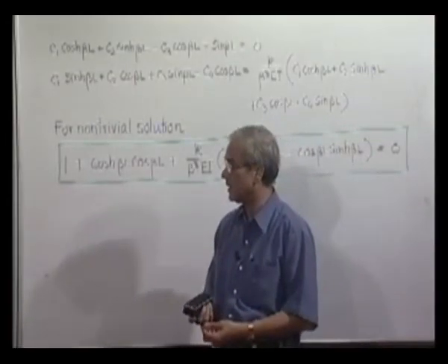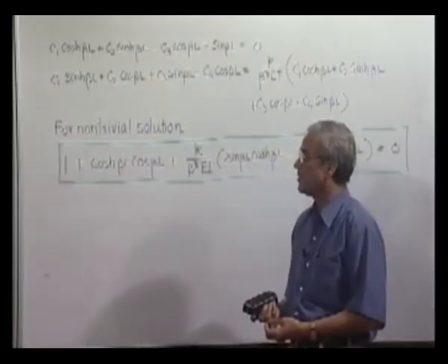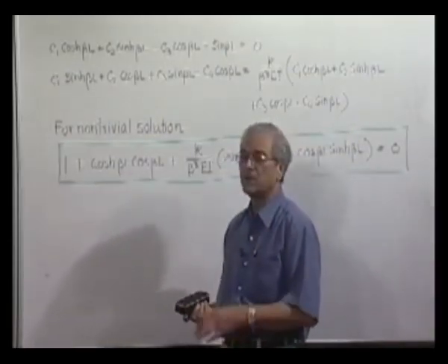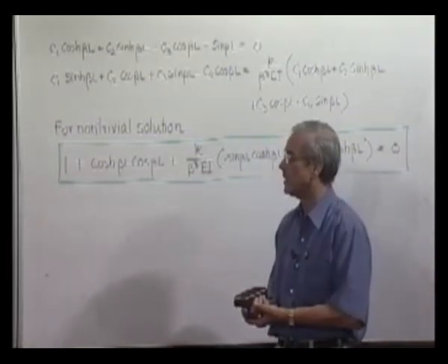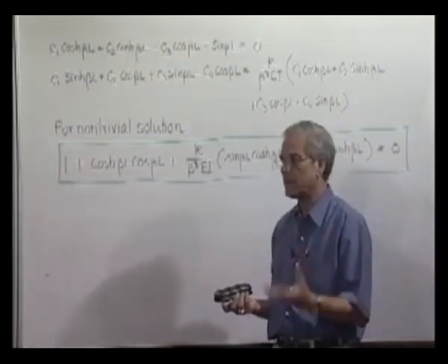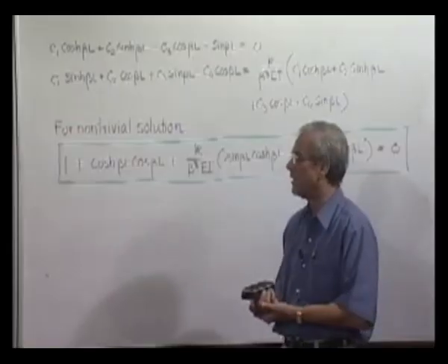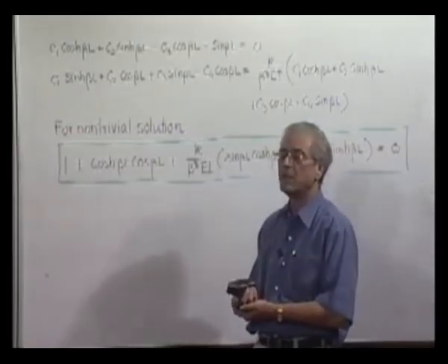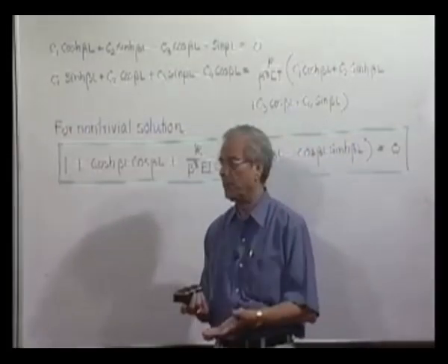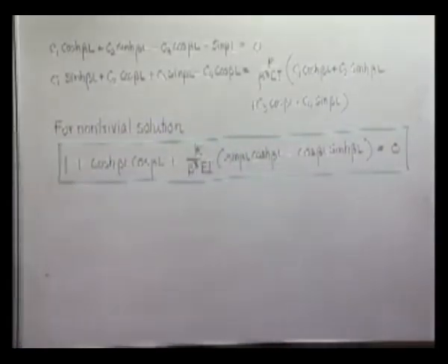Therefore in such cases the solution we can get either by numerical method, and nowadays with computer we can employ finite element technique, or otherwise when the designer of the machine is interested only in the fundamental frequency and also only an approximate estimate within plus minus few percent of error, then the problem can be solved in an approximate method. And therefore now we will take up those kinds of techniques which will give us approximate values of the natural frequency in cases of more complicated geometric situations, like the beam is not uniform and cases are complicated.